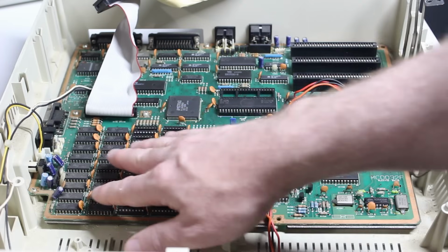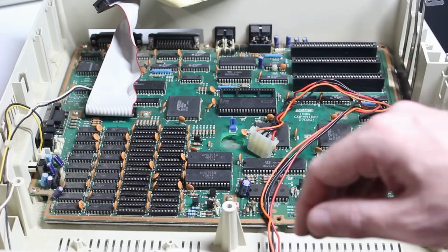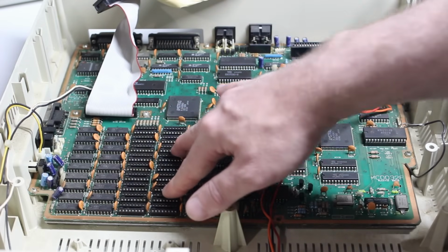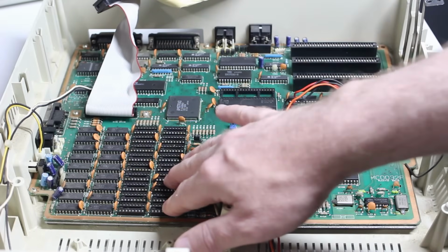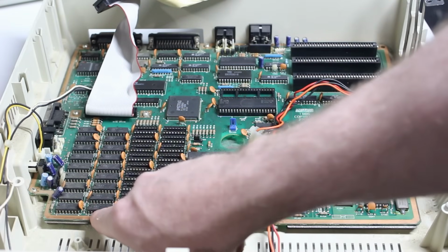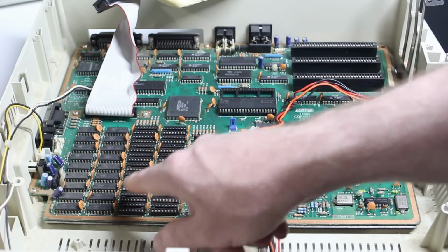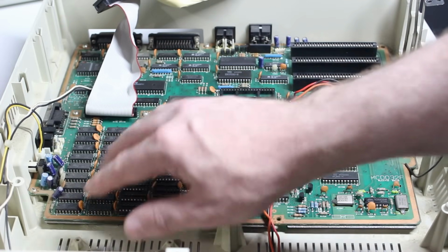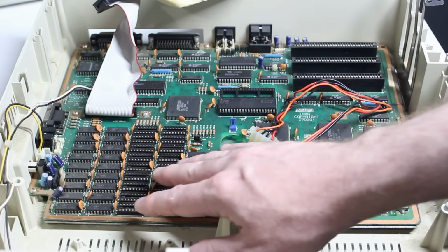And there's a couple of other chips for parity. Obviously you can add some additional chips here to bring the total up to 640K, but those chips are not here. Now, the important thing about these is that these are dynamic RAM chips, which means that they need a pulse every few milliseconds to refresh the contents. Otherwise, the machine will just crash.